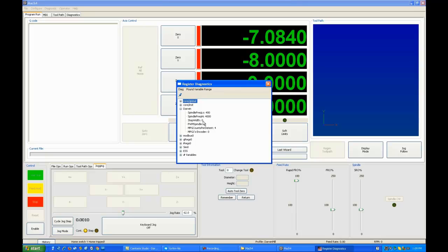Step width is to allow you to add a few microseconds to your step width pulse. Your step pulse you could add 5 to 10 microseconds, but it lengthens the time that you're in the interrupt. So you should leave this at 0 unless you need it, and then inch it up one at a time to see if it makes your system respond better. You'll need it if you've got a system which is badly losing steps. You may want to bump that. If it's only intermittently losing steps, a 1 bump will probably fix it. You can try it at 5 or 10 if you have a real rough system, just to see if that's the cause. If it isn't, move it back to 0, because this is a time waster.